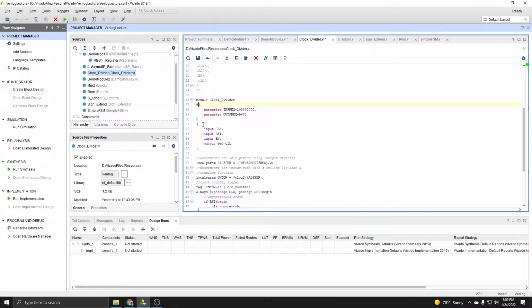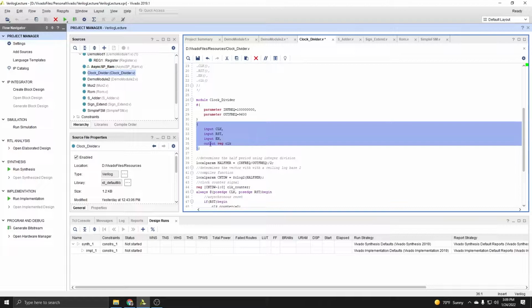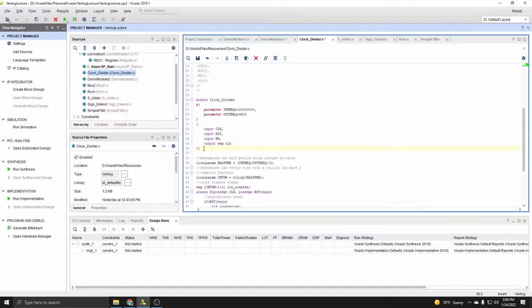And the next section that you see here, enclosed in the next set of parentheses, directly following, is the input-output ports. Now, there is a third mode, in-out, but you won't be using that in this class for any reason, though it does exist. The main two forms that you're going to use are just simply input and output. You can see here that I have input before each and every single one of the ports.